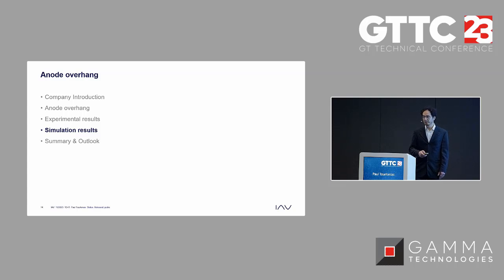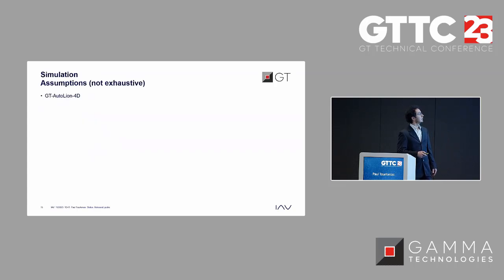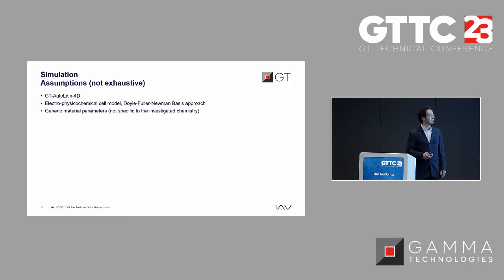Now coming to the simulation. We wanted to look at that phenomenon with GT-AutoLion, and we use for that the upcoming, I think, GT-AutoLion-4D, so maybe you didn't hear about that, which is basically a P2D model based on the classical Doyle-Fuller-Newman approach, and which is extended for some different parameters, especially the 3D discretizations that we have here in order to build up the geometry.